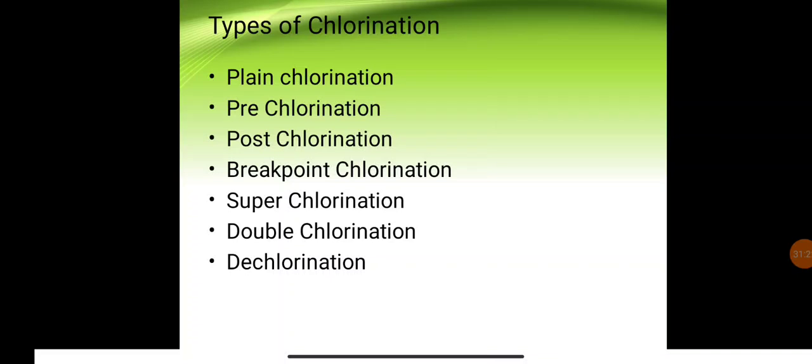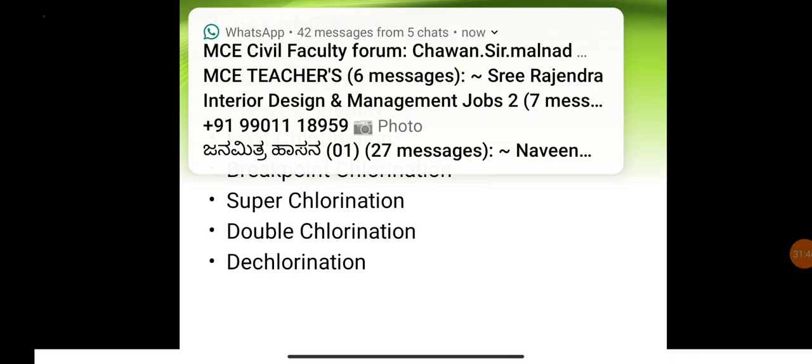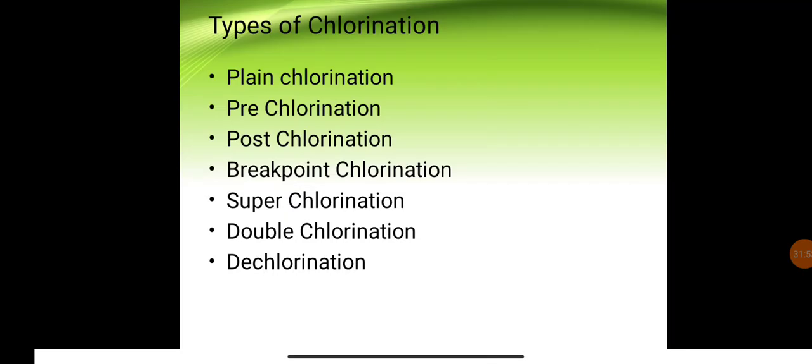That means at that particular time there is no consumption of chlorine for the process. Whatever chlorine we add remains as free chlorine, since nothing of it is utilized. That point we call breakpoint chlorination.